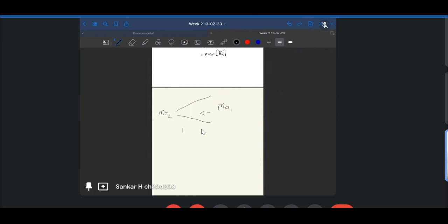So your inlet would be subsonic, and the exit will be supersonic. Not supersonic, sir. The Mach number will be less than one because it's just a converging section. So velocity has to increase over this region. Yes, sir. But then if the inlet is supersonic, the Mach number decreases until one.